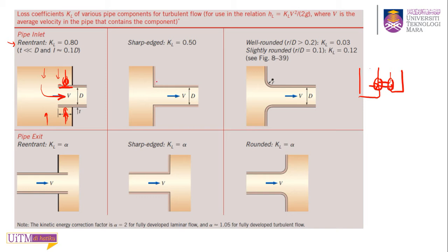Compared to this connection without that protruding entrance, where the flow goes straight into the entrance, you reduce the loss here, so all the flow tries to get into the pipe inlet. But because this is a 90 degree bend, it is still difficult to enter, the flow will bump around a little, so this will create a loss. That's why your loss coefficient reduces from 0.8 to 0.5.